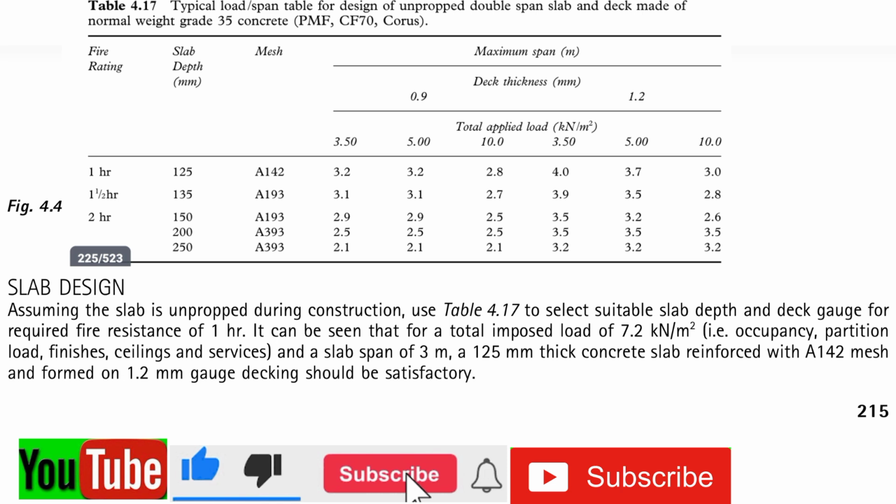Slab design. Assuming the slab is unpropped during construction, use table 4.17 to select a suitable slab depth and deck gauge for the required fire resistance of 1 hour.